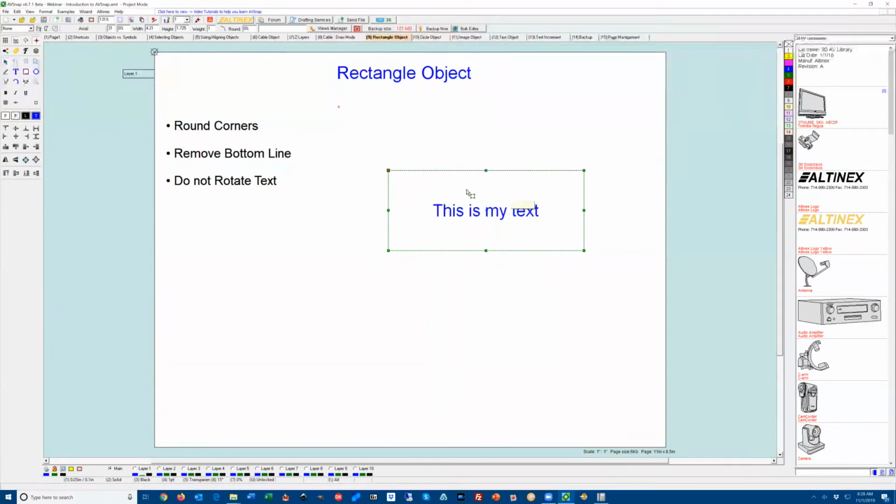If you want to adjust this position, you can use letter H to move it to the right, left, or center. Or you can use letter V to move it down: above the rectangle, within the upper line of the rectangle, below, below the rectangle, within the lower line of the rectangle, and finally in the center.